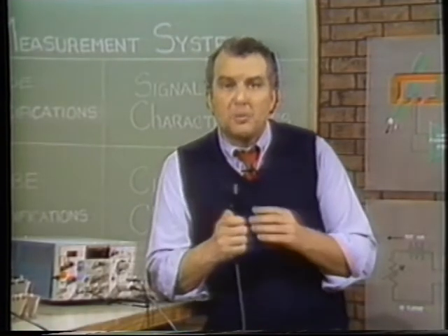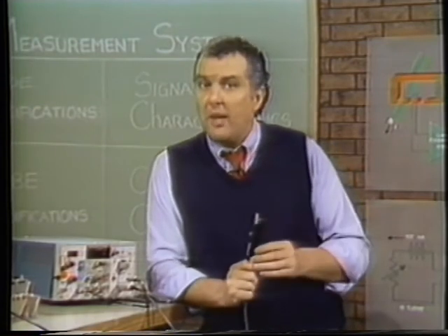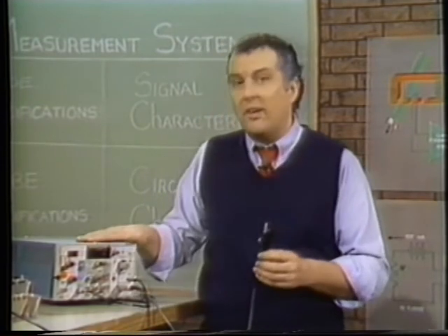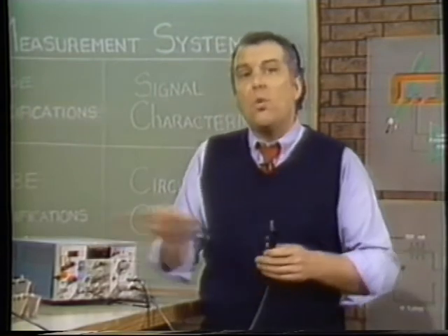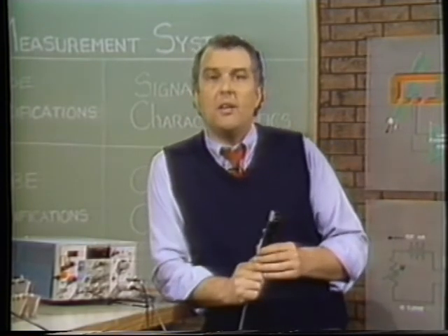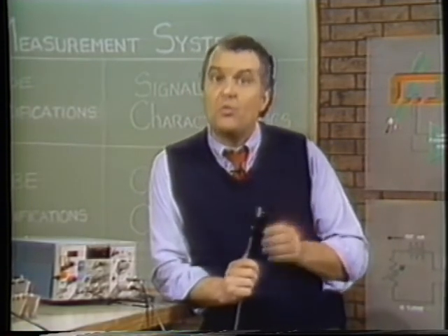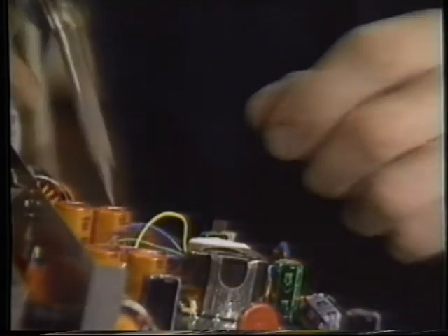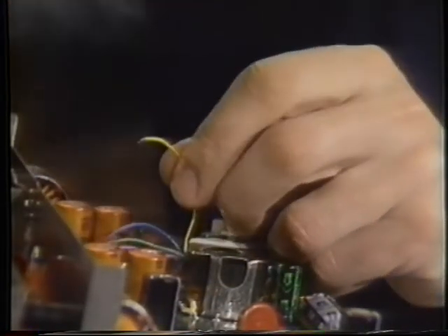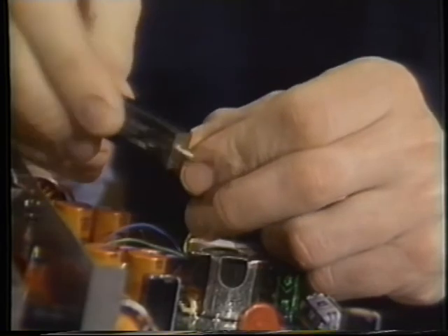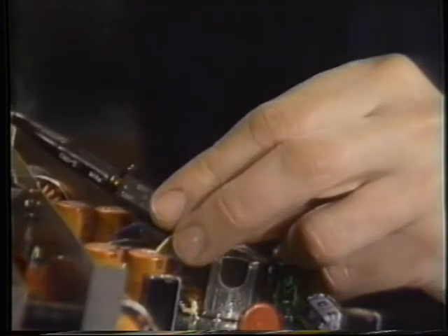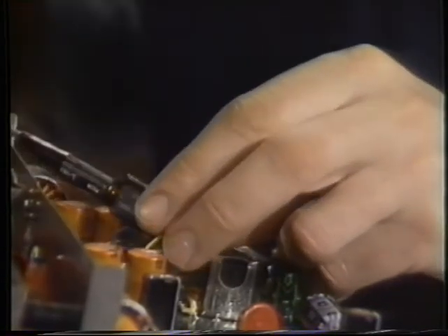You can increase split core sensitivity and extend its bandwidth by using a current probe amplifier. Fixed core current probes call for a little planning because you have to pass the wire through the core. For example, we can open this circuit and then insert the wire and probe in series. Usually, fixed core probes are permanently attached as calibration sensors, for example.